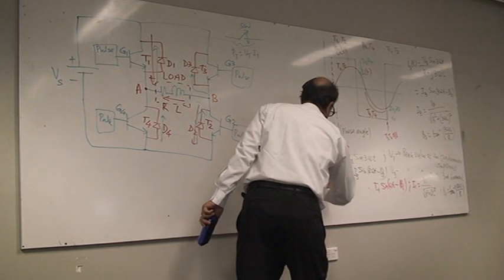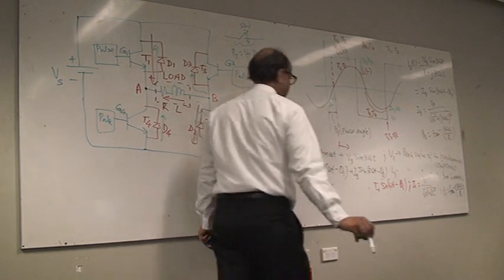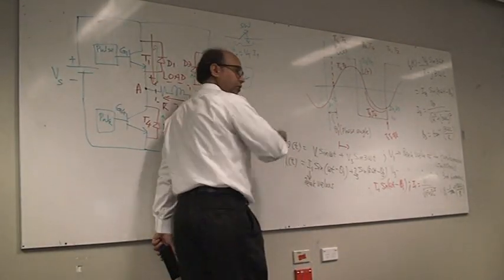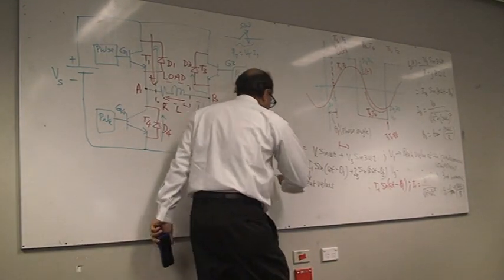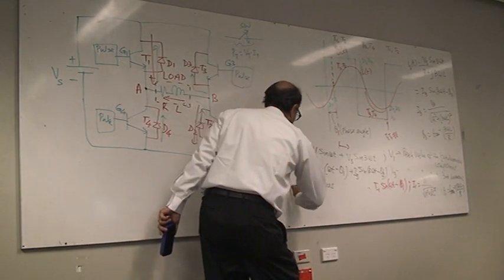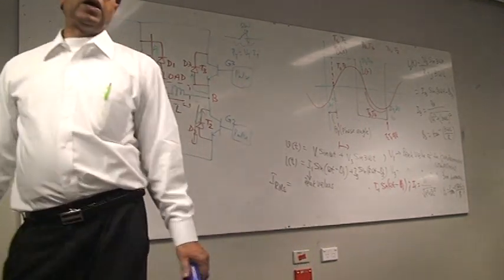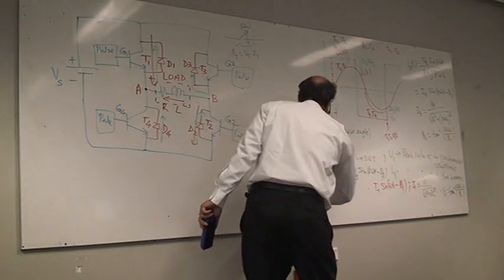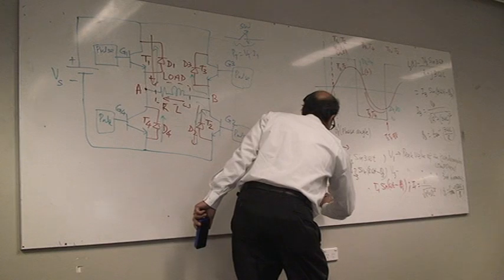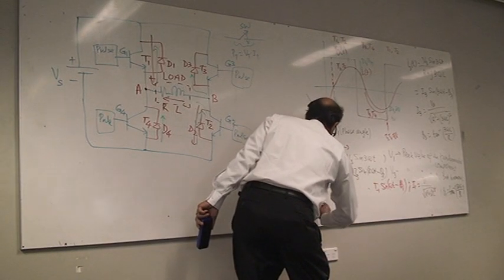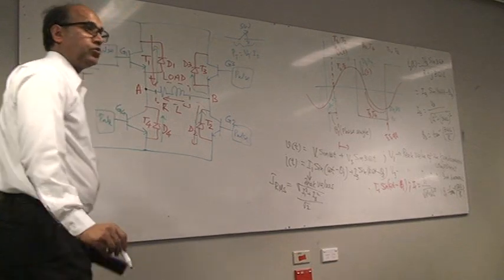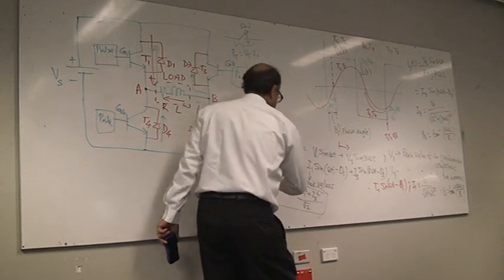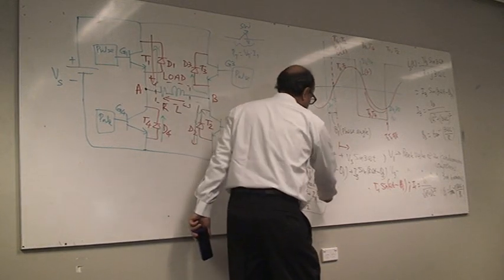Okay, these are the peak values for any alternating wave. You have to take the peak value. So RMS value, of course, you have to divide by root 2. So if I ask you what will be RMS for this, for each component you take, you get square root of I1 square plus I3 square, and so on, and then you divide by root 2. That's the RMS value you will get.